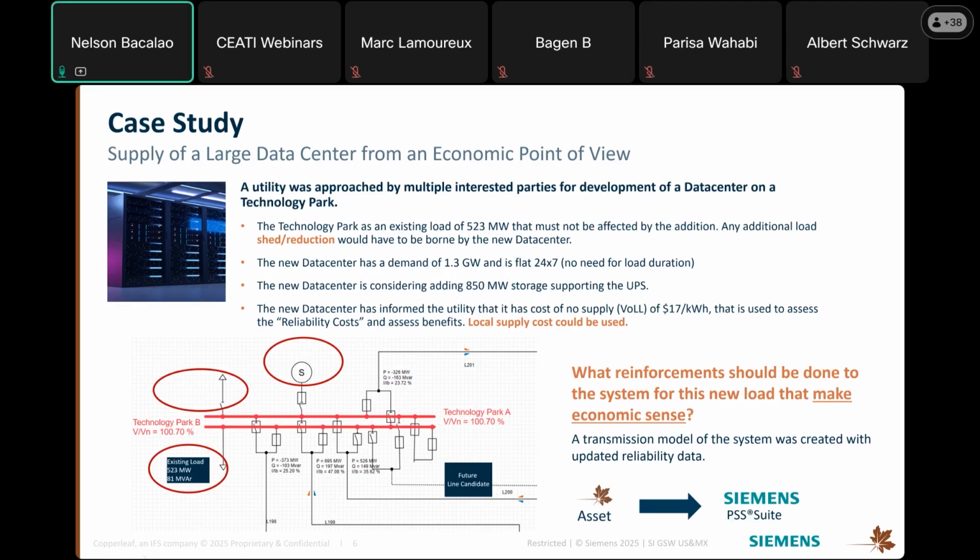So we don't need to worry, in this case, about what we call the load duration curve. And the concept there is that if on a system you have the load that varies over time, then you're looking at two events to happen simultaneously. The fault occurs, the overloading occurs, the need to shed load occurs, together with the load being at that level.